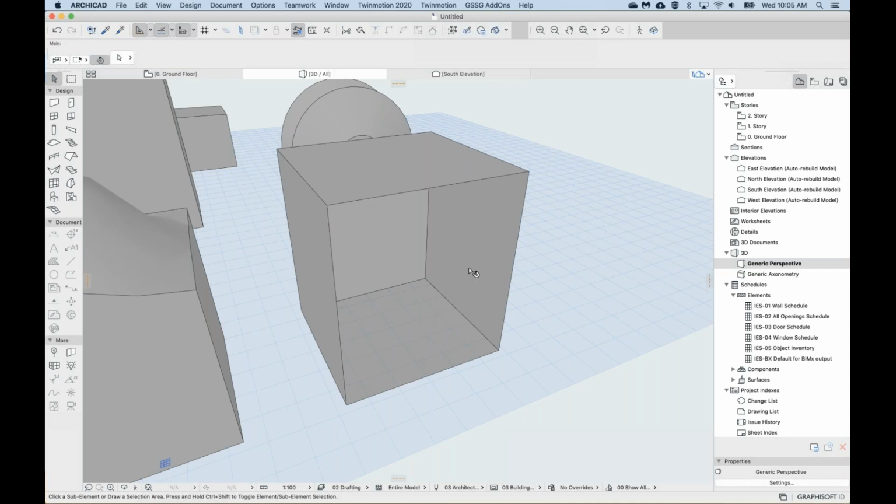But for now, we'll just click one surface, and then we'll delete it. So arrow tool, choose the white arrow. There's a solid arrow and a white arrow. I've clicked the surface and I've hit delete.